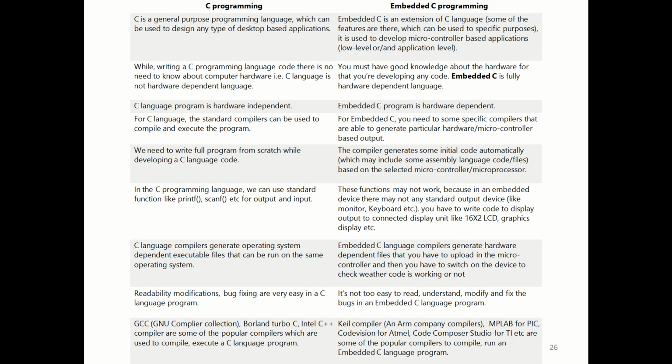Keyboard means always an ASCII keyboard. But now tell me, which system has an ASCII keyboard and computer monitor? Does your AC have one? Does your refrigerator? Does your washing machine? Nowhere. You may be having LEDs, LCDs, 7-segment displays, touch screens, sensors, and so on. So printf, scanf, the definition is not the same when it comes to embedded C.